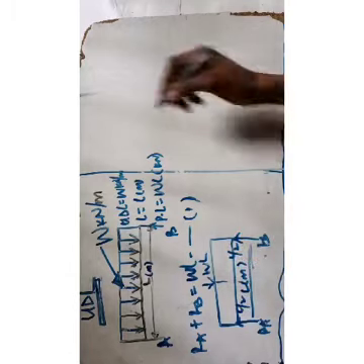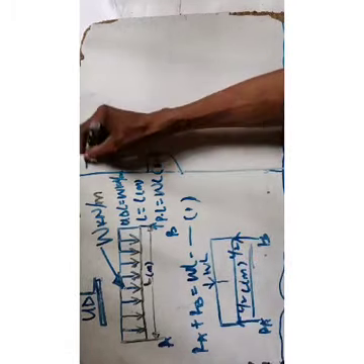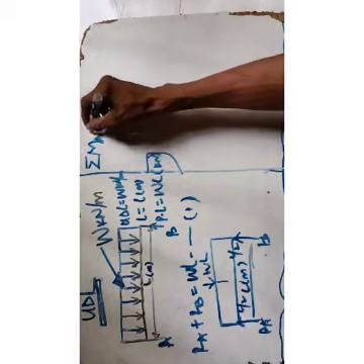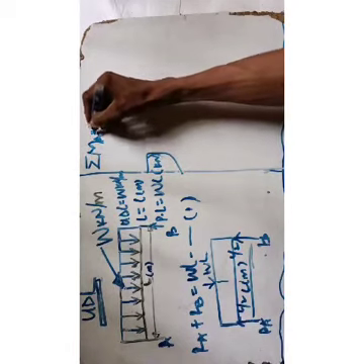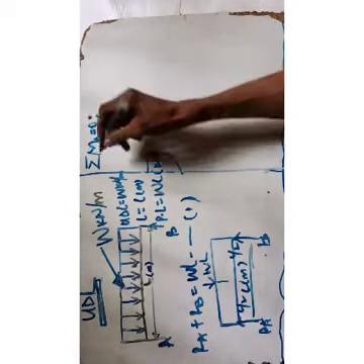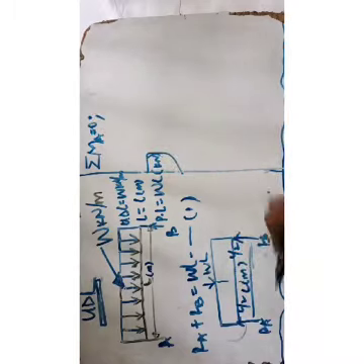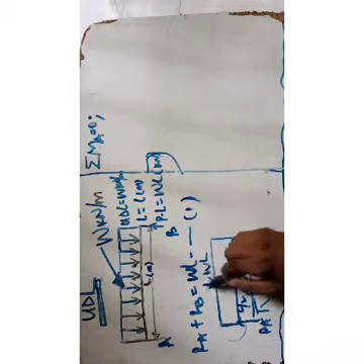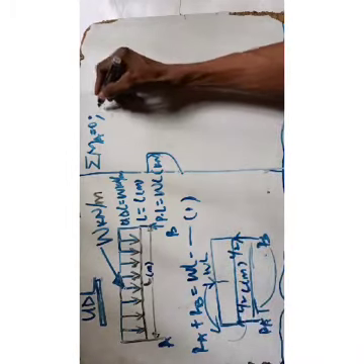So you take moments. Now taking moments at point A, you can write it like this: summation of moments at A equals 0. If you take moment at point A, all force will redirect itself back to A. That means this will cover the total length L, and this one will cover half the length. That will now be equal to 0.